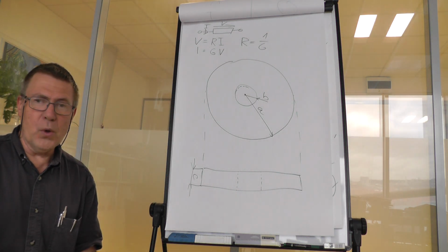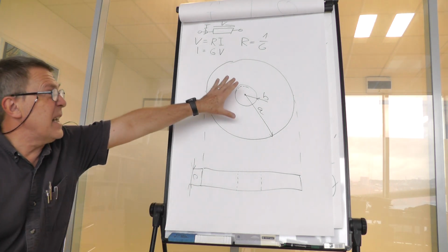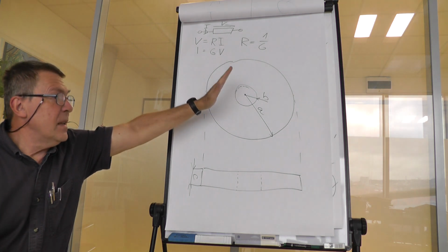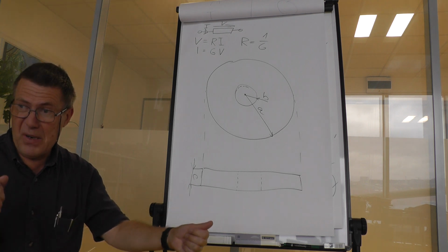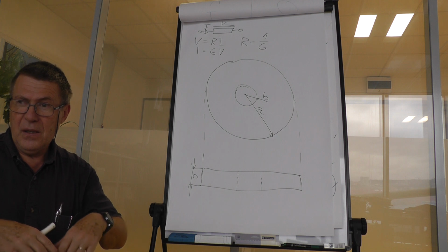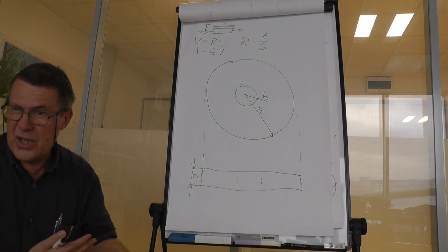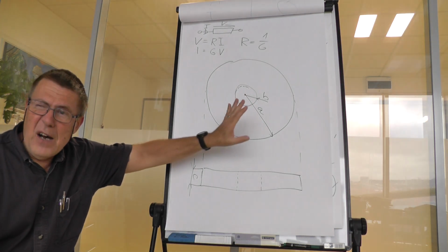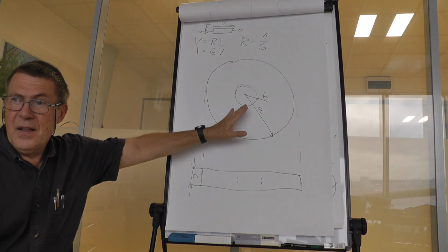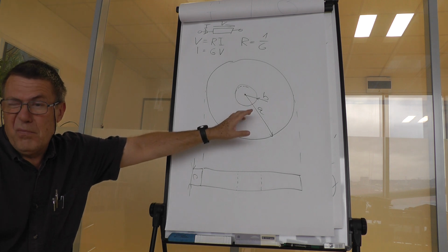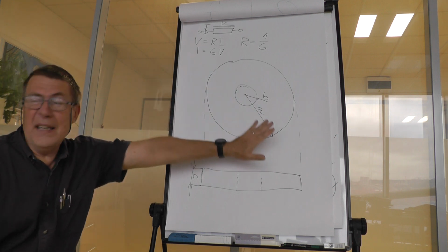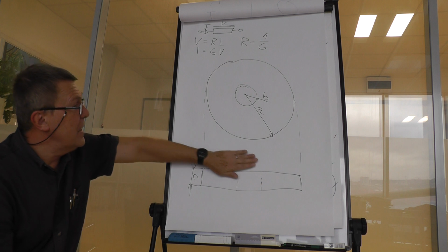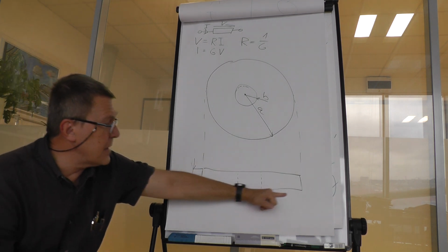Well, for example, we would use vacuum deposition. Let's say that the disk is from some conductor but not a perfect conductor. For example, it is a piece of carbon. Now we can put the disk into a vacuum chamber, heat it a little bit so that it is hot. Then we can evacuate the chamber, wait a little bit so that the disk loses all the gas which is inside the disk. After some time we can put there a very hot gas, for example of some metal, for example silver, and it would sit on the disk, and we can in that way create two electrodes, one upstairs, one downstairs, so we would have the disk contacted in the way that there would be one contact and the second contact.